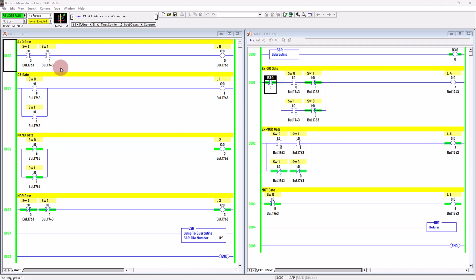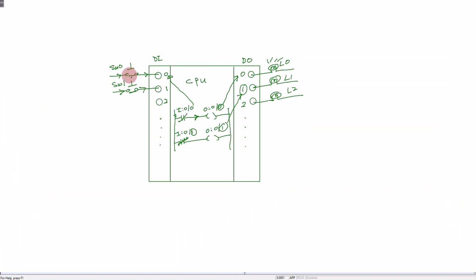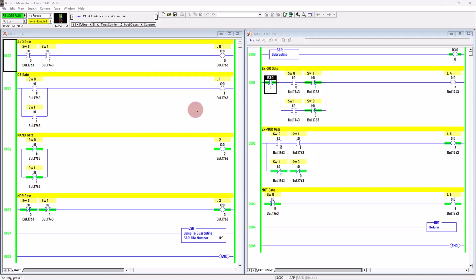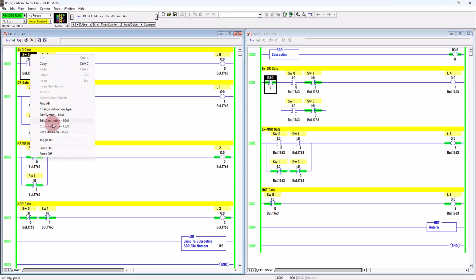Okay, let's say I will simulate this switch 0 pushed to close. So what happens, actual current will flow through digital input terminal point 0 and energize this LED 0. This will cause a relevant virtual switch to trigger from normally closed to open or from the originally normally open to close. Alright, now I trigger this to close.